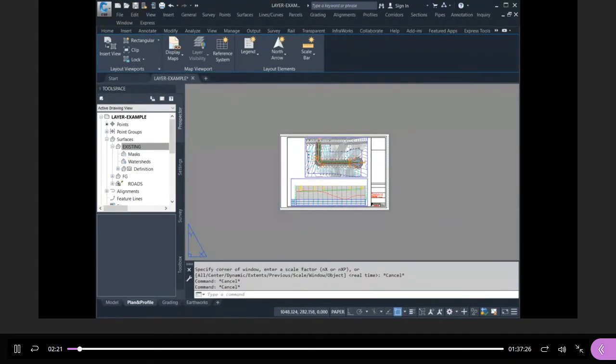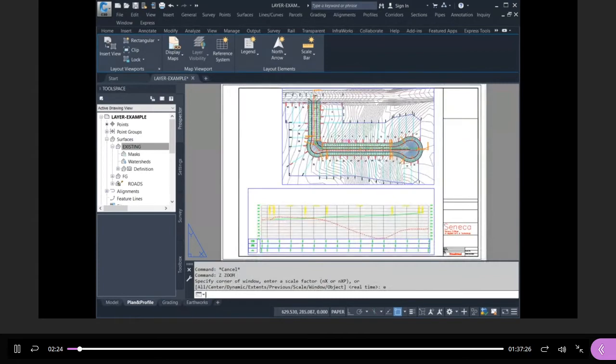The purpose of this drawing when it comes to engineering and construction, the contractor uses this drawing to actually build all of the services. So sanitary sewer, all the information they need is here. Storm sewer, all the information is here. Water main, all the information is here. And all the related items, right? So for storm, it's not just the pipe and the maintenance hole, but it's catch basin, it's head walls, anything related to servicing. Whether it's sanitary, storm, or water main, that's servicing. That's what we refer to as servicing.